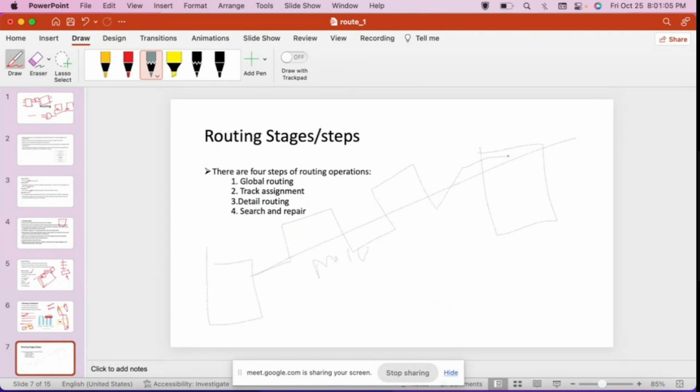So the maximum length of the routing layer is also mentioned, and minimum width, minimum spacing, maximum width, maximum spacing, and set preferred routing. So if I say metal 1 is horizontal, then metal 2 should be mostly vertical, HV fashion. I already said HV or VHVH fashion.